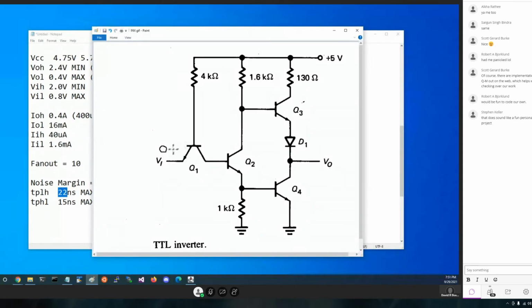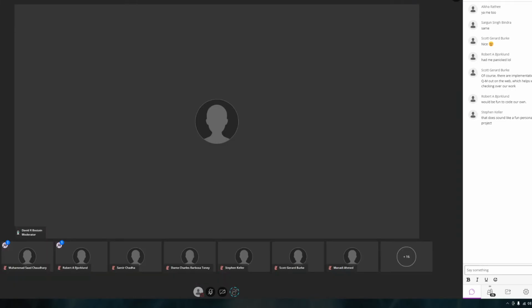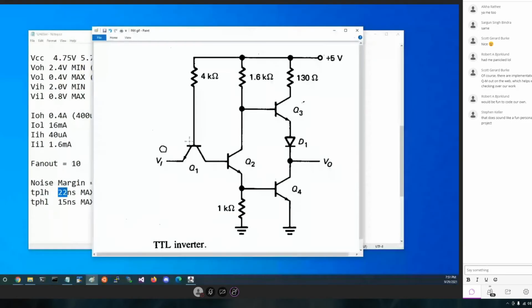If we lower the base, then we should be able to look out the base and see some power. If we look through that resistor, which is a limiting resistor, we do see 5 volts. Because of that, there can be current flowing through here. These transistors and resistor values are designed to be either saturated or cut off, so we would expect this one to be saturated, just as he said.